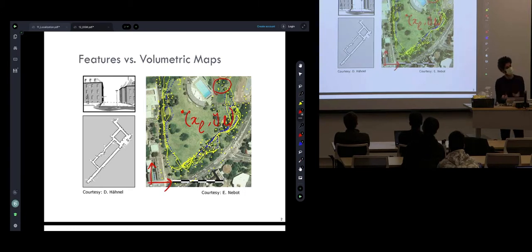Now, the challenge is, of course, that in this case, we don't know the locations of these landmarks. So the research is on SLAM, simultaneous localization and mapping. Not only do we want to recover the localized trajectory, but also we want to estimate the location of these landmarks, because we only know them relative to the sensor frame at each time step as the vehicle navigated the environment. So this is a SLAM problem, but if you know the landmarks, this is one way to represent the map, and we can use it for localization.